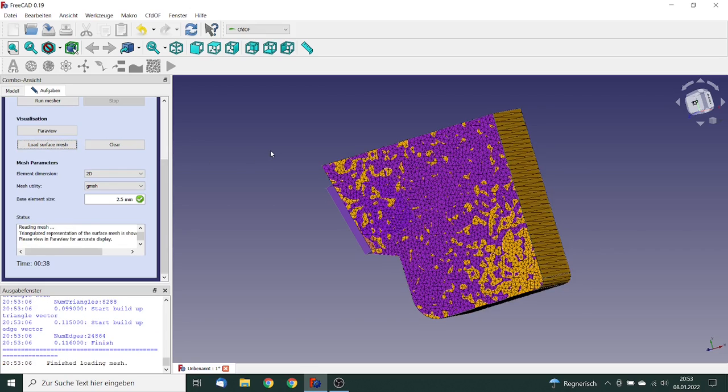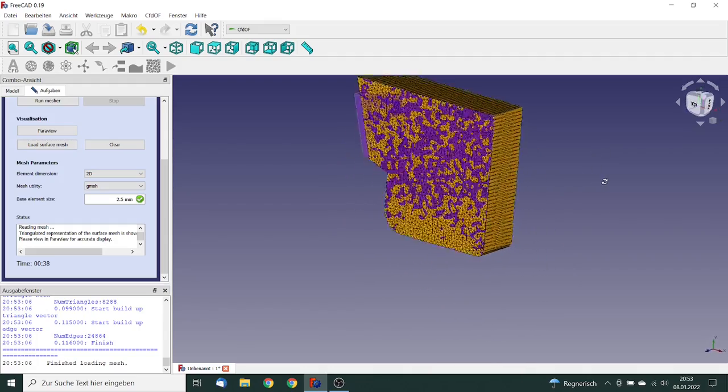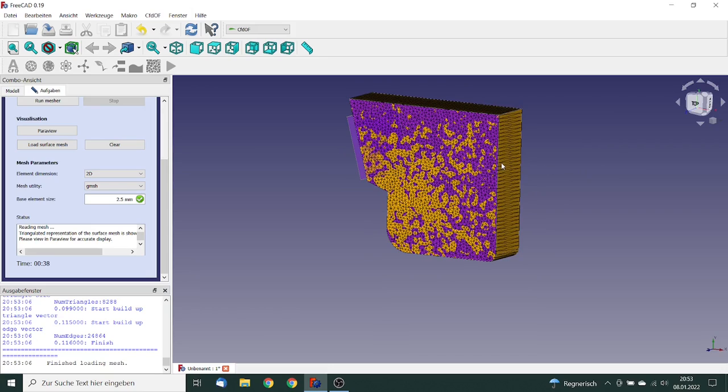So meshing was a 2D meshing, and when you look at the front side, it looks like a two-dimensional meshing, but in this direction, this is the Z plane. So in the Z direction, we see that we have elements. So in a way, it is a bit like a three-dimensional, but only with one element. But internally, it's calculated two-dimensional, and so the volume flow is only calculated in x and y direction, not in z direction. So this is how CFD computes a two-dimensional simulation.